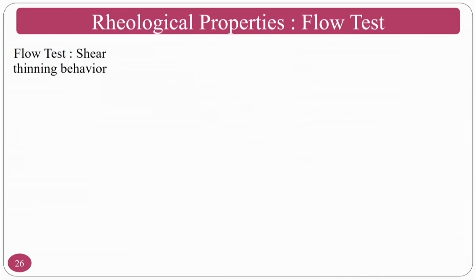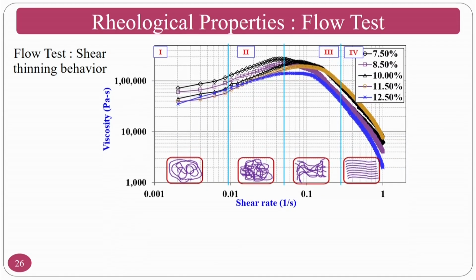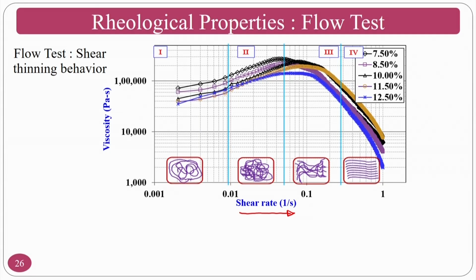Okay. So, if you see the analysis, as the shear rate increases, what is going to happen here is the abrasive medium will experience more rotational effect from the tool master. If you see any curve, what is happening is, when the shear rate is low, that means that your top rotating plate is rotating at slower speeds, because of which your polymer molecular chains climb one over each other and resist the flow.